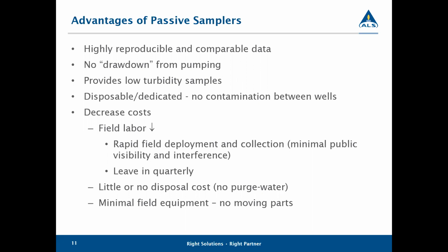You're not getting any turbidity in your samples, again, because it's just passively diffusing into the DI water inside the passive diffusion device. You don't run into those same issues that you get with pumping or purging.